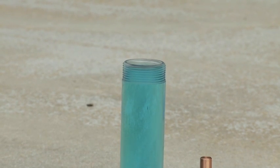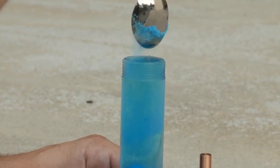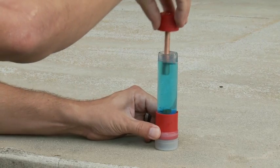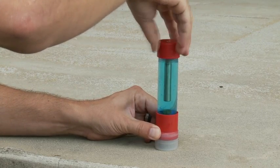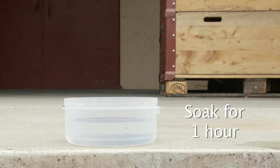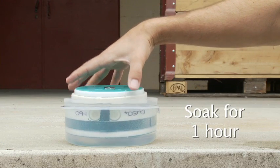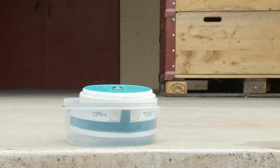To guarantee that the solution remains saturated, add an additional teaspoonful of copper sulfate crystals into the electrode. To prevent drying out, close the cap immediately. To prepare the wheel electrode, soak it in water for 1 hour. The wooden plug is not intended to be removed. Immerse the wheel in water well before you intend to use it to allow water to soak into the plug.